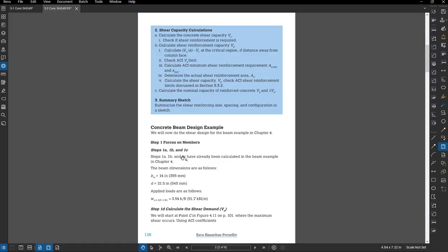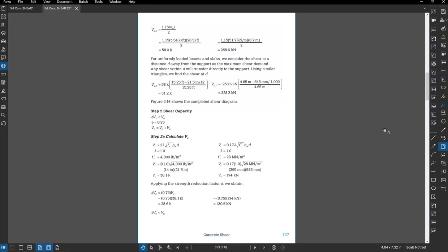So all of the examples that are typed out like this will start with how we got the shear demand, Vu. And this is important. You can't just pull it out of the hat. It doesn't come out of a book. You need to calculate it based on the applied loads to the structure and a good healthy beam analysis, where we're calculating, in this case, shear. And in concrete, we actually need to know the shear variation along the length of the beam, as we saw. In steel and timber, not as much, because usually the sections are the same along the length of the beam.